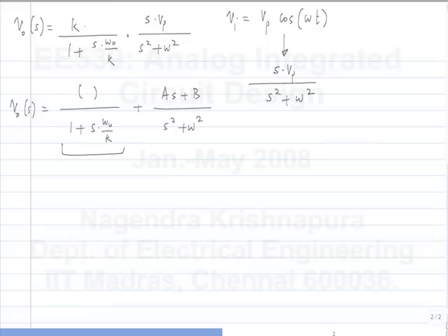If you look in the time domain, what does this give you? Exponential. It gives you a decaying exponential. What does this give you? Sinusoid. It gives you some sinusoid, right? So this exponential is a result of the pole of the system, or it's a natural response of the system. So you have some transient. Eventually this part will die down to 0, and you will get the steady state sinusoid. How can we get the steady state magnitude and phase directly?